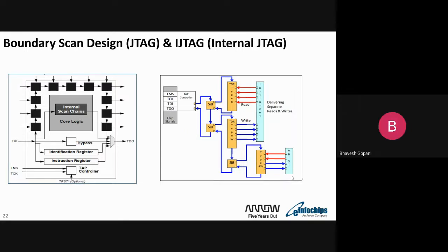Yes, functionality, because the PLL is an independent IP. Let's say the PLL is already verified by someone, so we just need to plug and play in our environment, in our SOC. The purpose of the PLL is that we want to generate a certain frequency. Let's say if I want to generate 1 gigahertz as an output, my input reference would be, let's say, 100 megahertz.